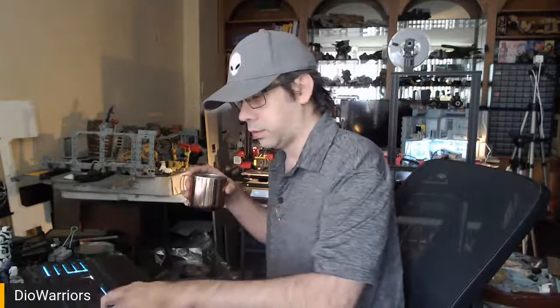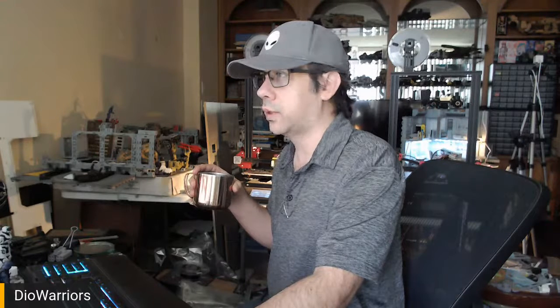So okay, we take this, we go mate. We want to select that surface, offset it by 0.25, select this surface, and then see which direction. Okay, we want it up. Then the mate's already there.